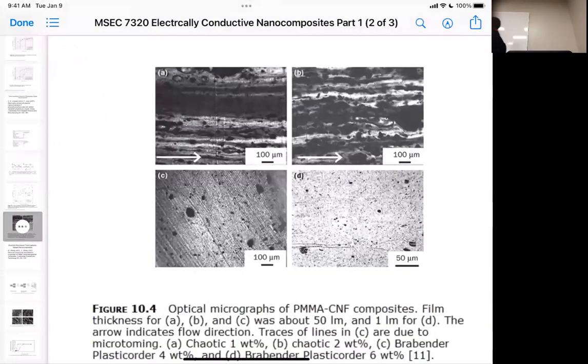So could we do this industrially? Yeah, because most industrial lines tend to be continuous and linear. You get your shear flow to go continuous and linear, you can actually produce this on a pretty good scale. All you have to do is design your system to have the shear in the correct direction. Then, let's say you made it as a fairly thick sheet, then you draw it out, get even higher.